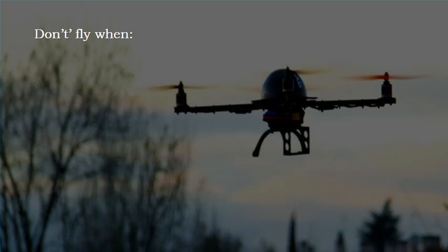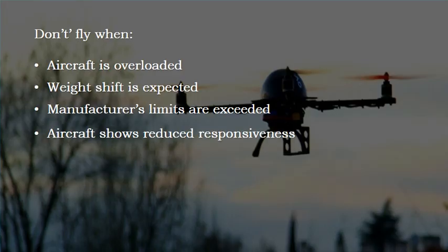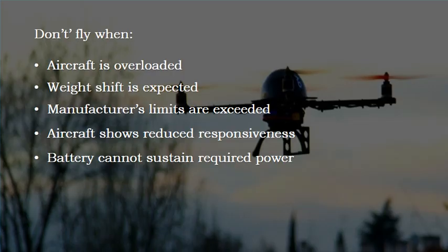You may be asked, when should you not fly based on performance? Considerations not to fly are when the aircraft is overloaded, the weight shift is expected, the manufacturer's limits are exceeded, the aircraft shows reduced responsiveness, and the batteries cannot sustain required power.